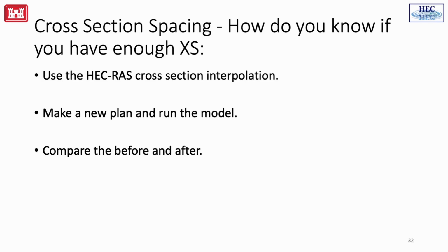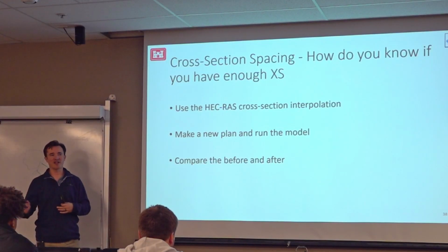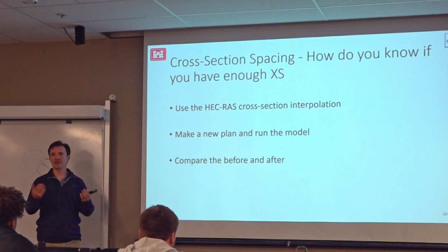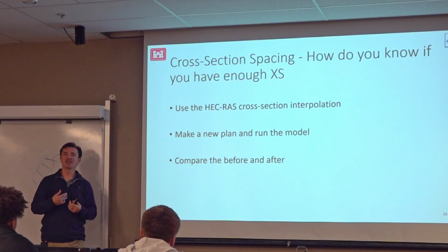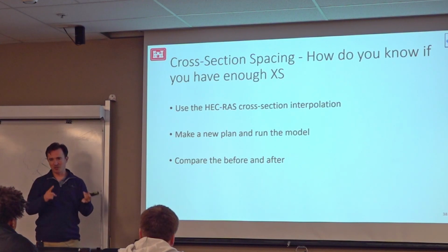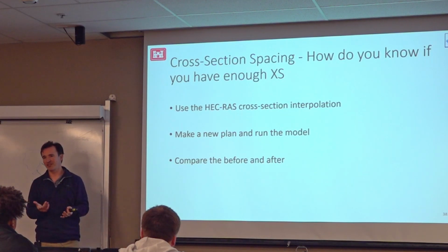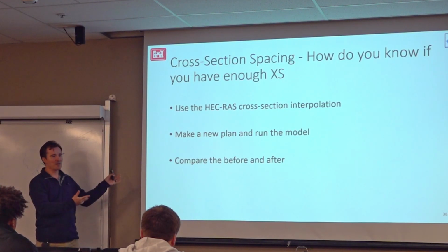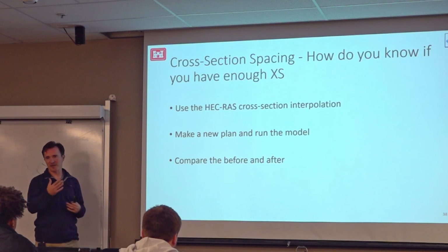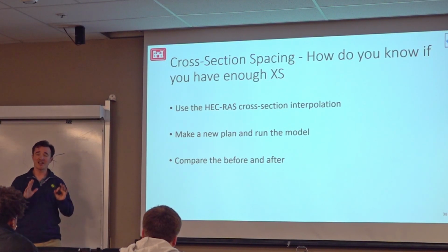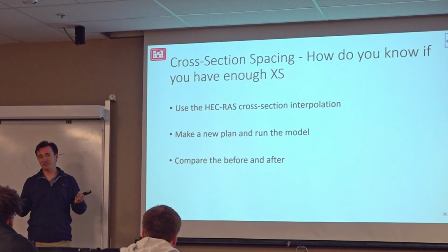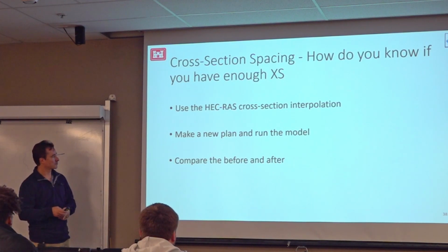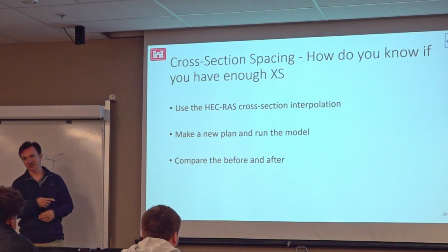When I get projects from people, I know if they're a beginner or an advanced user by how much testing they've done before they come to me with something. Like I say, oh, the model doesn't run, and they made one mesh and did one time step, then I know they don't know what they're doing. But if they made a mesh and tried lots of things, changed their spacing and tried different time steps, looked at all those things, exhausted all of that, and it's still not running, then maybe it's a bug. So compare and iterate.